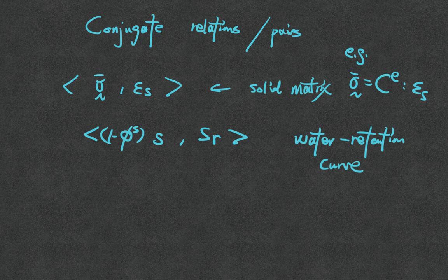So in your solid mechanics, you only need one constitutive law, and that would be the mapping from the strain to the stress. It could be linear, then you write an elasticity tensor. It could be nonlinear, where you use more things to describe it. It could be isotropic, so you just need Young's modulus and Poisson's ratio. And then we have the water retention behavior. Now, this is new. And now we still have the previous one that exists, which is the Darcy's relationship.